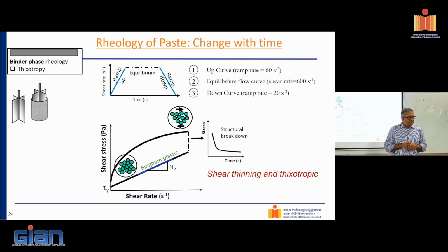Now the question is, will it still have the same slump value? Possibly not, right? Now, why is that important? Suppose that liquid is able to regain its yield stress very quickly. Then I have some faith that if I can produce a liquid that can be pumped, sheared, comes to rest and again regains its yield stress, it'll keep its shape,